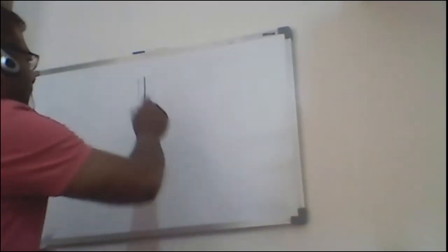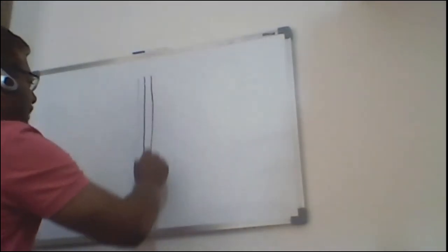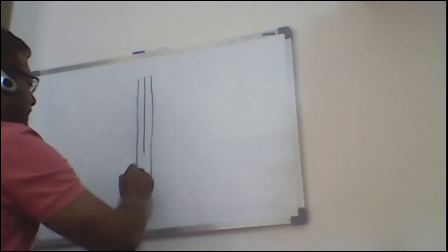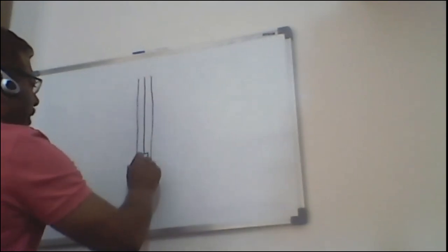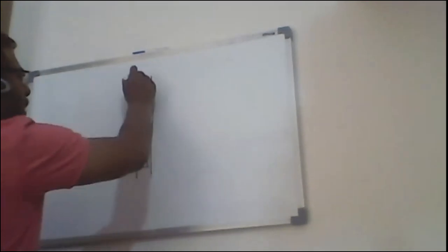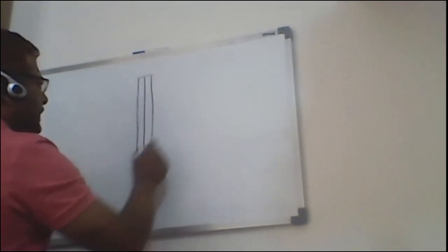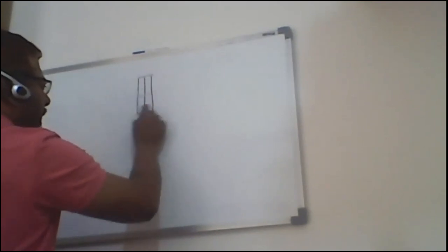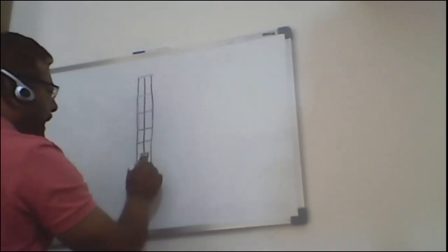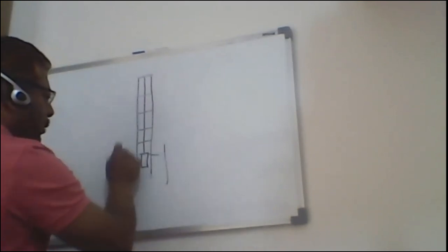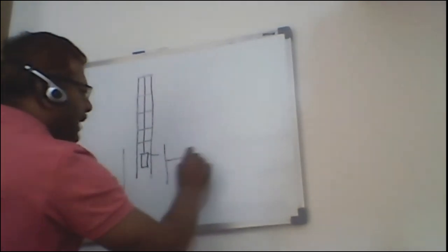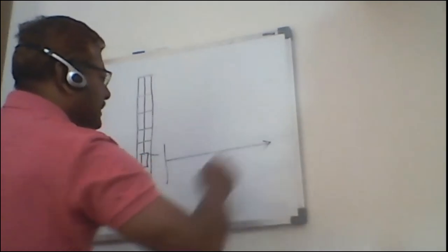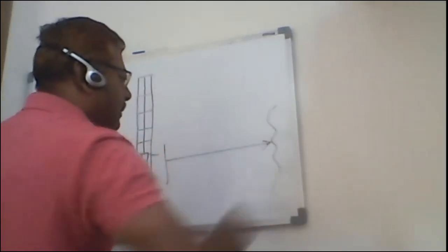Okay, so now in case of well testing, what we initially try to understand, let's say if it is a drawdown test, we allow the well to flow. So initially, we have the compressible zone within the well. Then it is coming to a skin which is around the wellbore. Then we get a continuous or infinitely acting reservoir, and then we get the effect of the boundary.